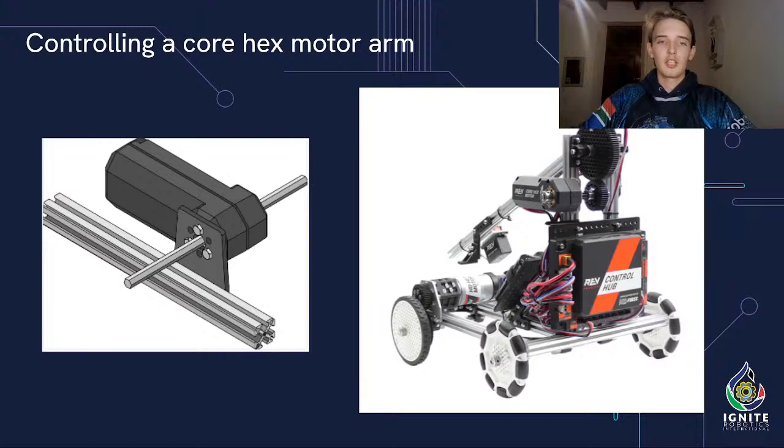So in the slides here, you can see if the arm's position was here, like it currently is, this is collect, this would be 0. If we wanted to move up, so it's kind of pointing towards this heading right here, I would guess, we can just say 90 degrees. Let's do 90 degrees around here. It just makes it simpler. So if we're doing 90 degrees, then let's say that the delivery position in this case is 100 ticks. And this would be slightly different for each robot, each motor, depending on how the hardware is built.